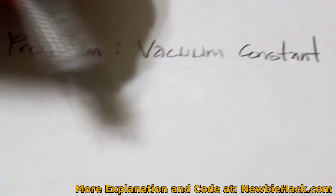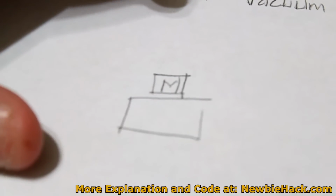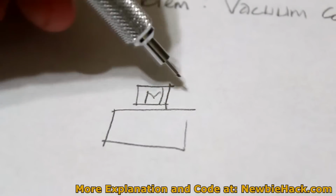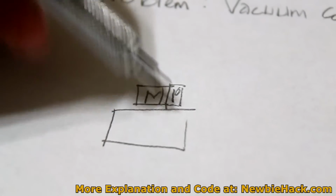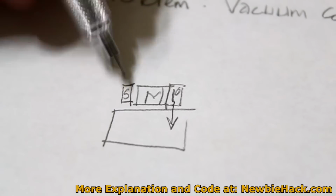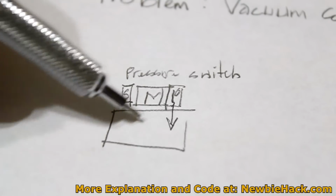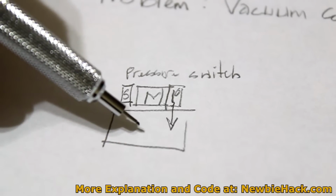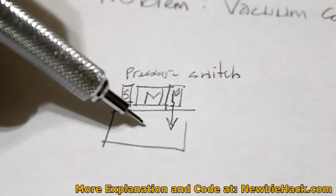In a compressor, you have the compressor motor, and then generally you'll have a tank that's right below it, or on the side of it. And the motor is constantly pumping, and you'd also have a pump here, pumping air into the tank. There also exists a pressure switch that turns the motor on when the pressure inside the tank is below, say, 85 pounds per square inch, psi, and would turn the motor off if the pressure in the tank equals 115.